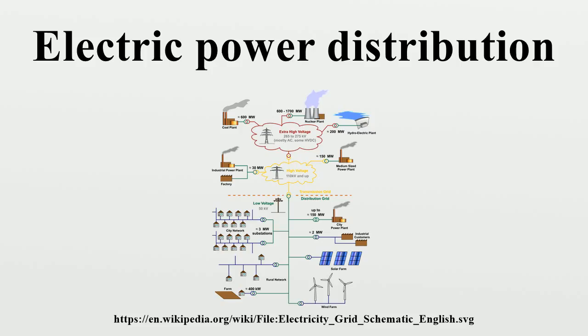Many areas in the world use single-phase 220V or 230V residential and light industrial service. In this system, the high-voltage distribution network supplies a few substations per area, and the 230V power from each substation is directly distributed. A live wire and neutral are connected to the building from one phase. Single-phase distribution is used where motor loads are light.